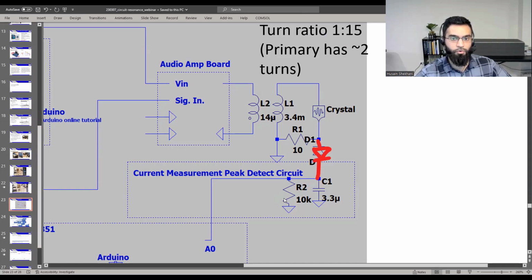But it'll be dropped over this resistor, which will bleed that charge off in order to reset that average. So it'll be a rolling average basically. And there's a time constant here. I think the time constant is like 3 milliseconds or 0.3 milliseconds or something. 10K times 3.3 micro is going to give you a time in seconds, and that's going to be your reset time. So if you make this like 2000 microfarads, you're not going to get any useful rolling average. So you can do those calculations, and the best way to know if it works is to try it.